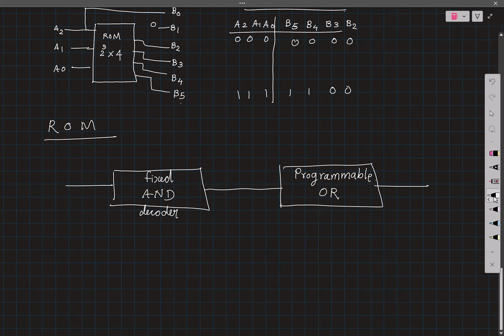So now this should give you some more ideas. If you were a businessman or a businesswoman looking at this, what is the second thought that will come to your mind? If I were to sell an IC with an array of AND gates and an array of OR gates such that they can implement all forms of SOP, this looks like a nice business idea.